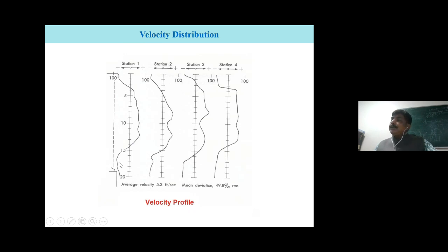So please do not assume that inside the ESP at every section the flue gas is moving in one direction. It changes its direction. Here it's a reversal. At the edges, top and bottom, because of the presence of the metallic body, the boundary layer, flow reversal takes place.